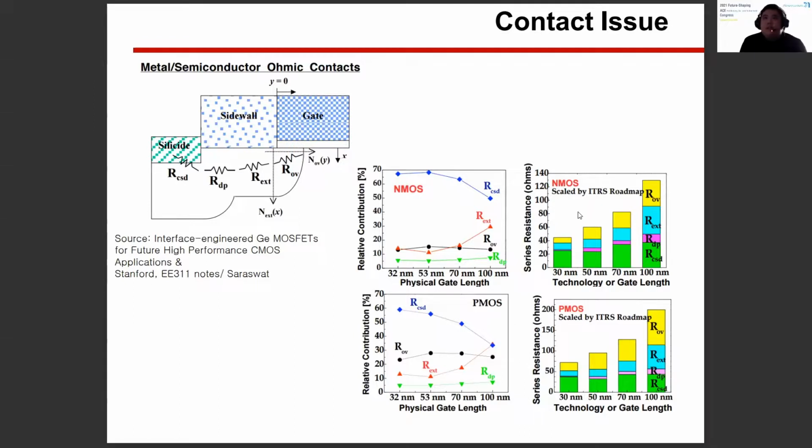With this, the resistances from other factors can be lowered, but because the contact is also narrowed, the contact resistance cannot be lowered that much by scaling down devices. So the resistance stays relatively high while the capacitance is lowered when we scale down devices.